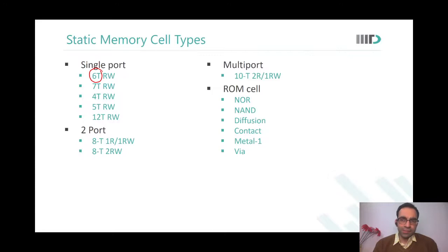But mask costs are significant, right? You anyway are making a mask, Raghav. You need a diffusion mask anyways. If you are programming the memory in metal 1, do you not need the diffusion mask? You will still need the diffusion mask. Yes. Right? Yes, sir. There's something else. It won't be diffusion, sir.